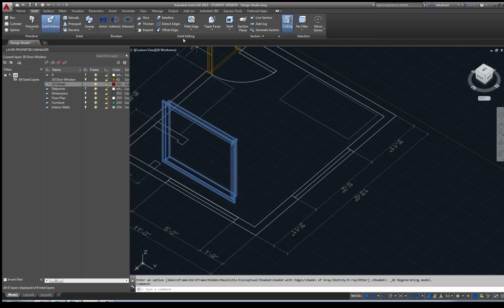So for the moment, I simply select this one and just move copy out, escape. Then this copy I'm going to rotate. So U, spacebar, there, click. Okay, great. And now I have to actually snap it back onto my wall.